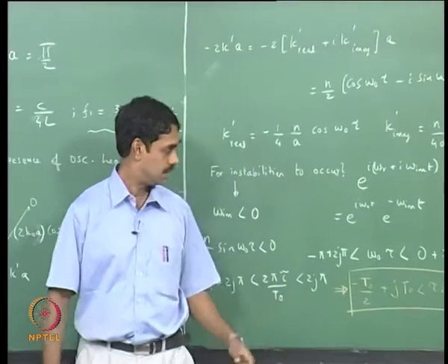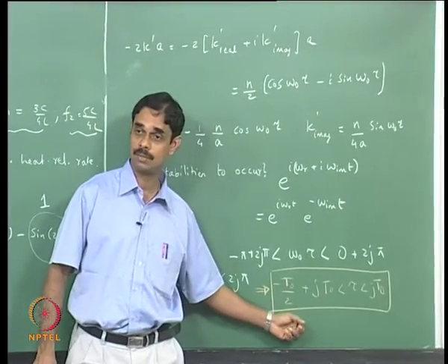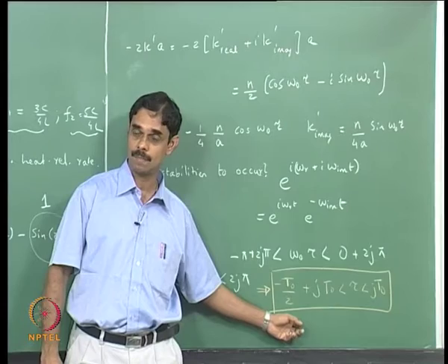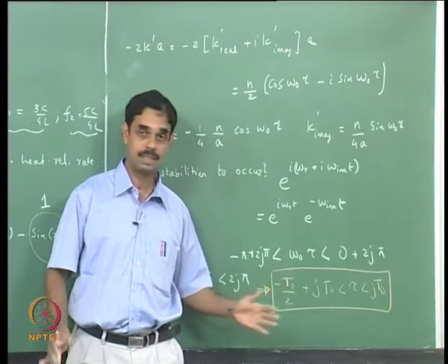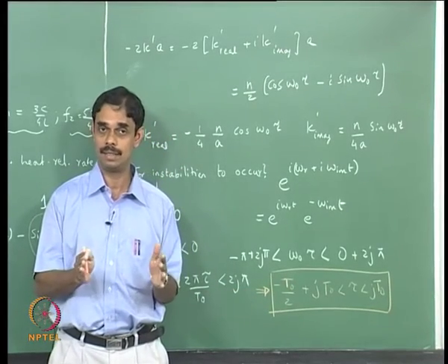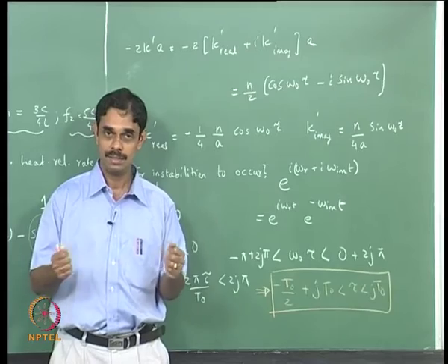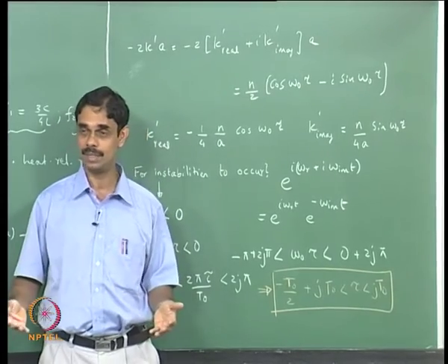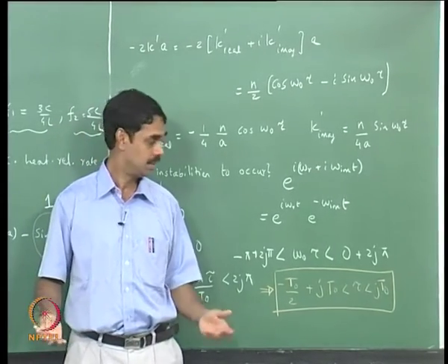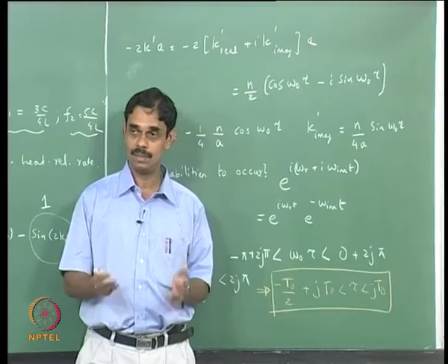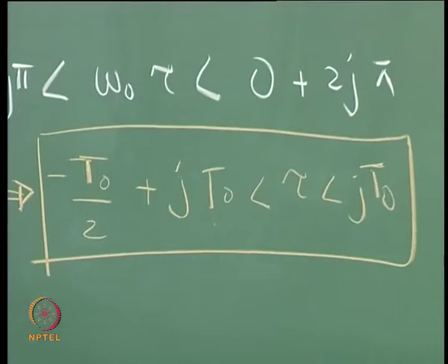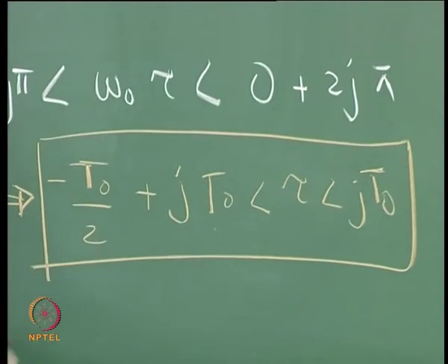Now, see, we have not included damping in our model as was pointed out in last class. So, the actual regime where you get instability will be smaller, because damping always helps to make the system stable. So, your instability regime will be smaller, and if the damping is really a lot, there will be no instability at all.